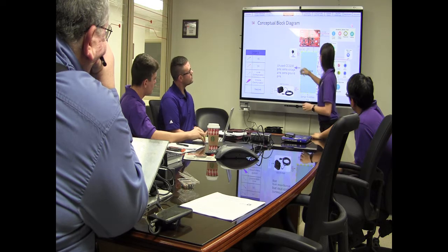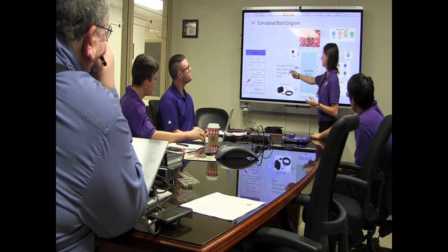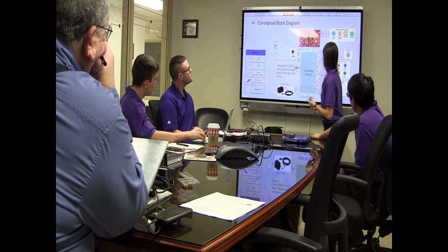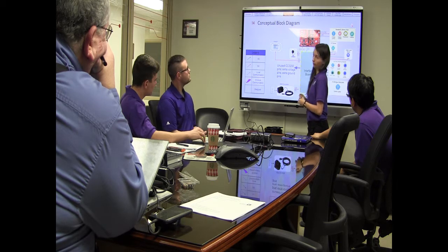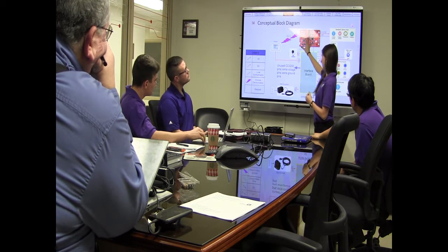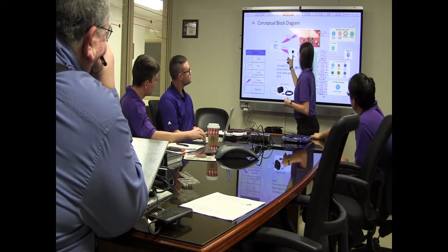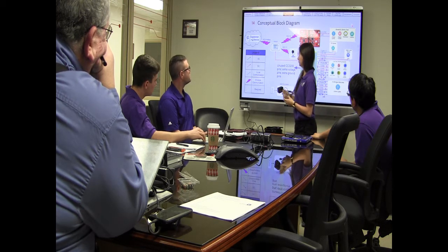So this here is showing that we are directly connecting the CC3200 to our interface board, and all those extra pins come through, and we're sending them out, along with extra voltage pins and extra ground pins. We are directly powering our hotspot from the interface board with 12 volts. And we have a Wi-Fi module on our CC3200 that communicates 802.11 to our hotspot. The WiseCam does that as well. And that sends 4G wireless to the cloud, which we're using Cayenne.